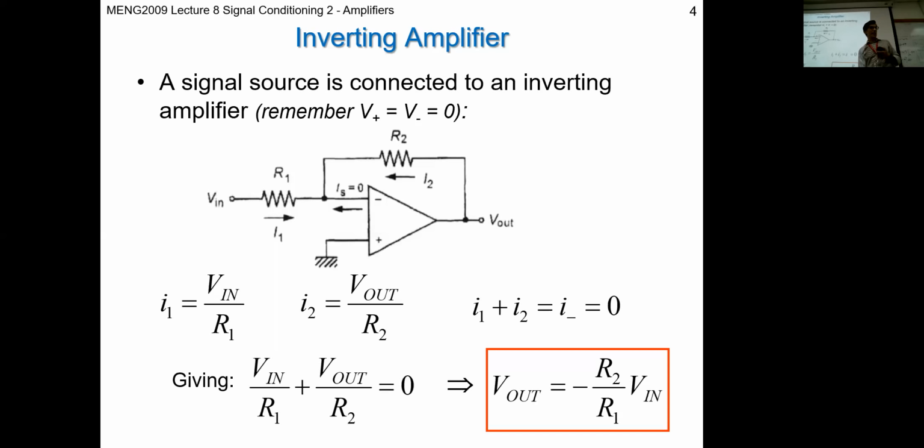That's going to increase the actual resistance of those devices, and you start to skew the output of your amplifier. And because the heating or the power dissipation in the two resistors is different, you're going to get a varied effect, and therefore the actual ratio or amplification is going to change as the thing gets hotter. So for that reason, you don't put 2 ohms and 1 ohm. That's why you put 200 kilo ohms and 100 kilo ohms.